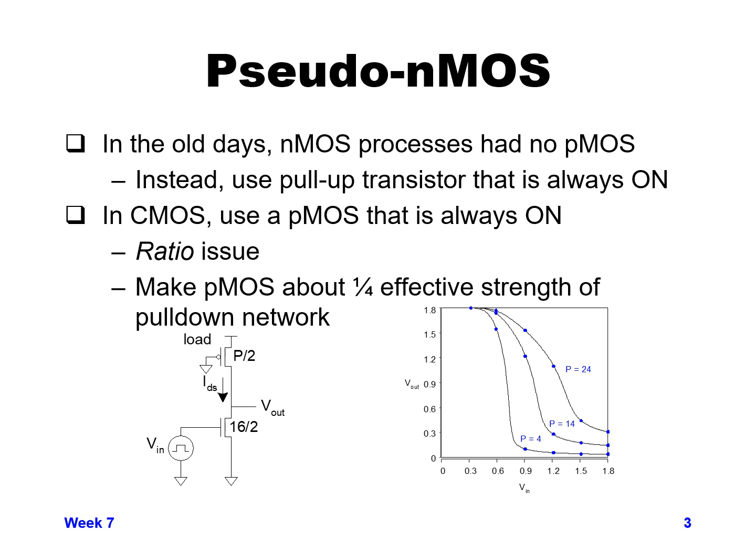Now, it's not going to be able to get all the way to 0 because the PMOS device is always on, always fighting the NMOS device, so it's going to get somewhere really far down into the linear region, and how far down depends on the relative strength of the NMOS and the PMOS to each other. And so here there's a ratio issue going on.